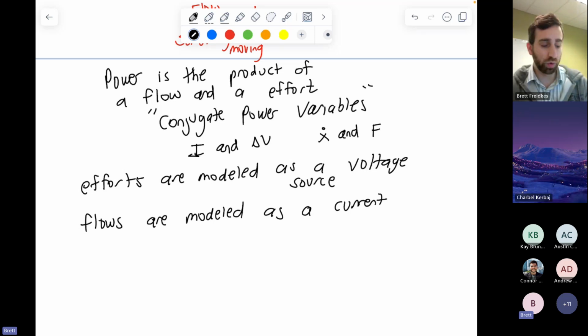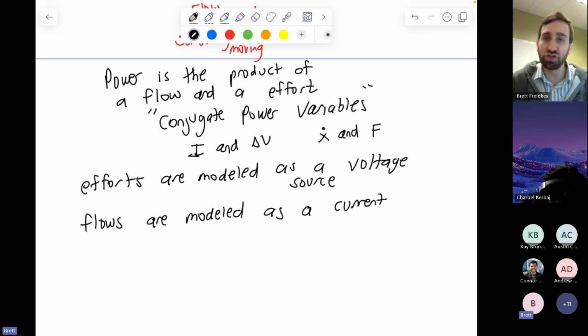We'll see that sensitivity plays a role here because if I have an effort in the mechanical domain, like a force, and it's going to produce something in the electrical domain, like a voltage output, we will draw a circuit that goes from the mechanical domain to the electrical domain. And if we do circuit analysis on it, we can find the ratio between that input force and our output voltage. And that's what gives us sensitivity ultimately. This is the whole benefit of doing this, is that we can understand the flow of energy in the circuit, and we can use that elementary circuit analysis to find information about how the transducer performs as a function of frequency.